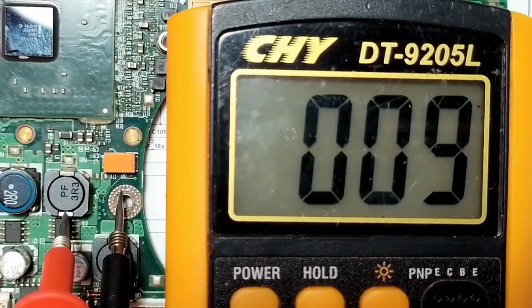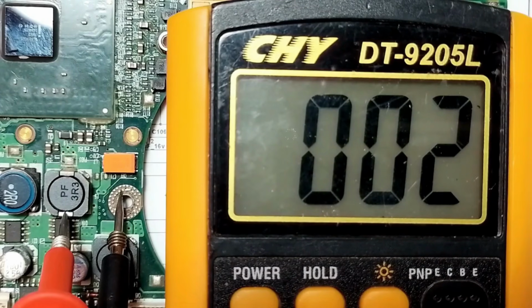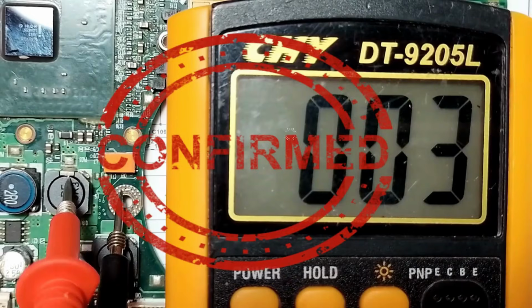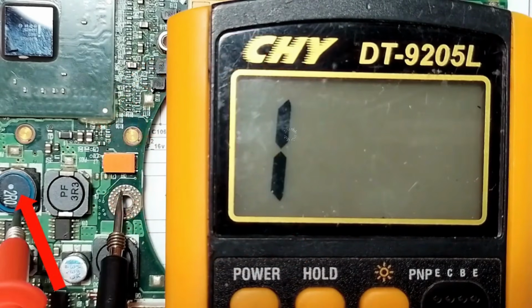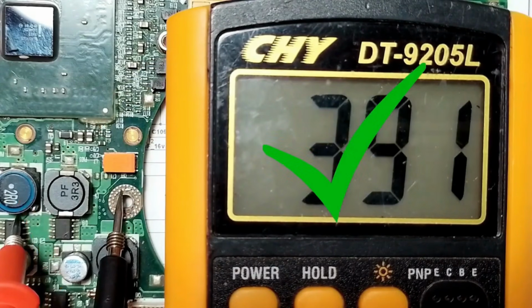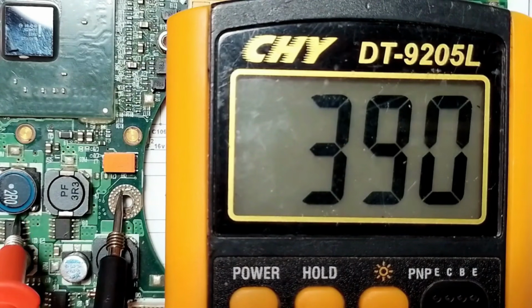So if we check, we get a 0 on the multimeter. It means the power goes directly to the ground, as you can see. We confirm the short circuit. But for this inductor, the second one, if we check it, as you can see, we get a reading. This is a good reading. We don't have a short circuit in the other channel.